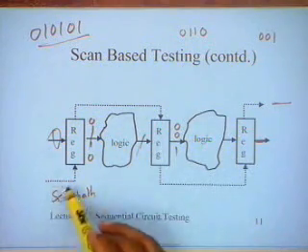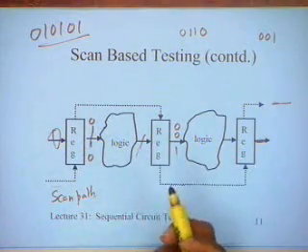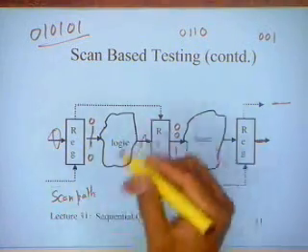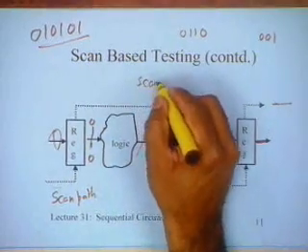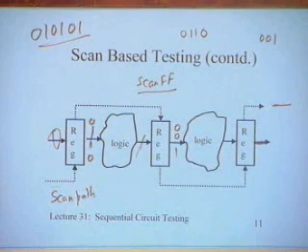If you look at libraries which are used for design, there are also flip-flops which are called scan flip-flops. What these scan flip-flops essentially mean is they provide you all these facilities for serial data transfer. They provide you the ports by which you can connect the flip-flops sequentially, and also the clocking input if a different clock is required to do that.